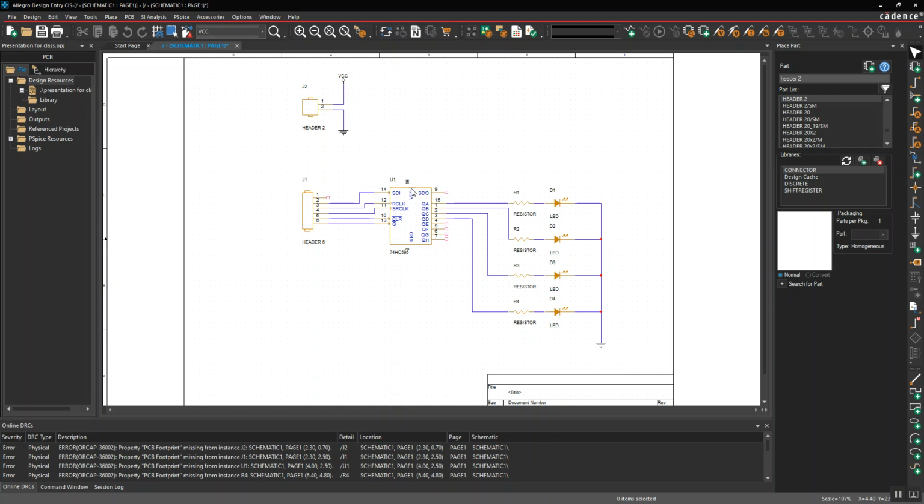These automatically link up to the VCC and the ground normally, but sometimes we want to show them, or we might have a different symbol instead of the ground or VCC if we have multiple power rails. So we're just going to do a wire coming off there and a wire coming off of here. And then we can just copy this symbol.